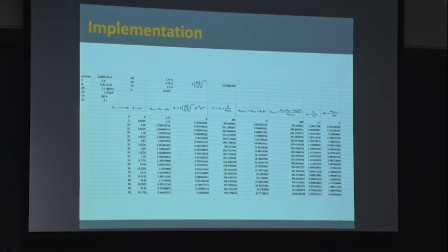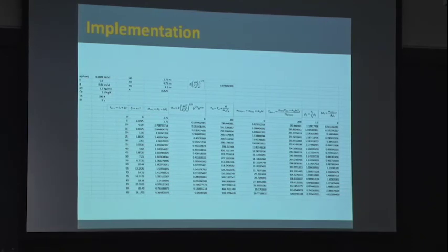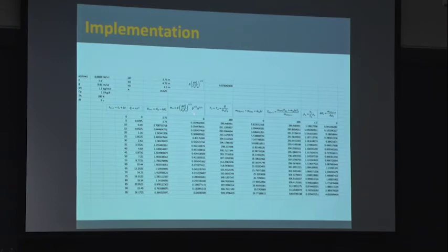Rate is actually 0 in the first step. Is that clear? So then once I have the mass of air entrained, I can calculate the temperature of the smoke, because I know MA, I know CP, I know Q, I know TA, but for my first step, I have 0 over 0. So instead of doing that, I just put the ambient temperature, okay? Then once I do conservation of mass in the control volume, which is the mass of the control volume in the previous step, which was 0, times the new mass of air entrainment times the delta T, which is 0.